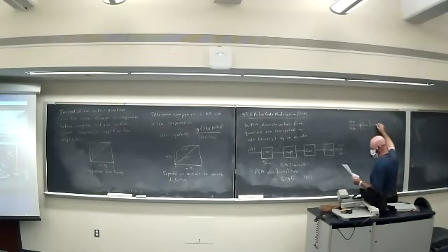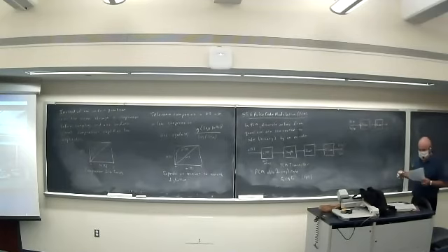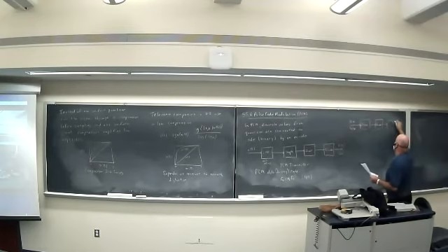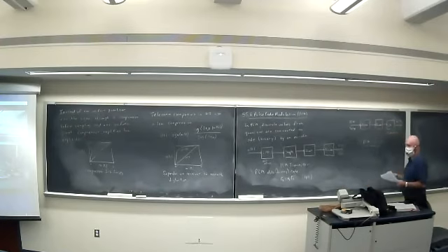We'll typically have a regenerator at the receiver, and then a decoder to convert the binary words back into voltage levels, and then a low-pass filter, which is my reconstruction filter. And then I get back an approximation to my original message.